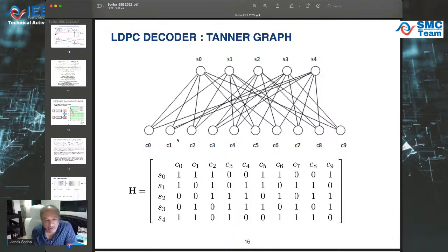What happens here is that an algorithm is used to scan across here and identify those code bits that provide evidence, probabilistically, that they weren't affected that much by the noise, and therefore need to be listened to. So if you looked at this and found that C0 and C2 and C1 were not really affected by noise, and there's a way of telling that, then you would weigh these bits heavily in your decoding algorithm, and in fact you would use these to correct the others if possible.